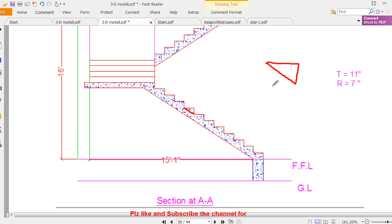Okay, this is my step, and the bottom one is basically my waist slab. This is my 9 inch. This is basically 9 inch. Okay, and the rise is 7 inch, and the tread is basically 11 inch.